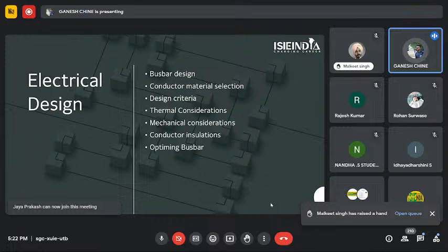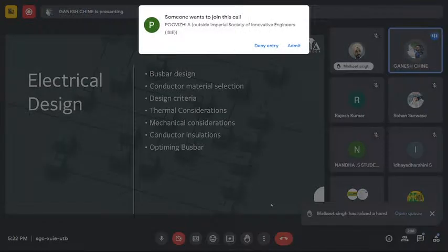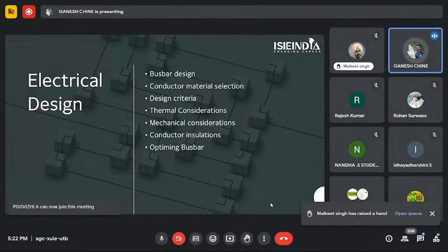When the resistance in the bus bar increases, there is joule heating, and the temperature of the bus bar gets high. If the temperature gets high, the bus bar material melts, and while melting, the molten metal spreads on the cell. At that time the cell also gets damaged, and if the molten material spreads on other wires, that system also gets damaged.